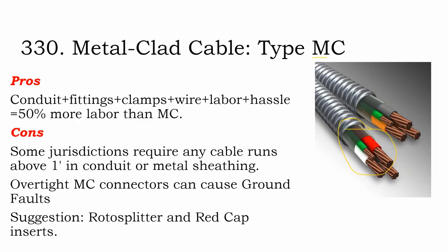And so the solution was, well, we'll run our metal conduit and pull single conductor cable through it. There is an option, though, for a bundled cable. It costs 3 times as much in material as buying the conduit and putting the cable inside of it. But by the time you add everything up, I find it worthwhile. I never regret having it on a job site when we can use it.